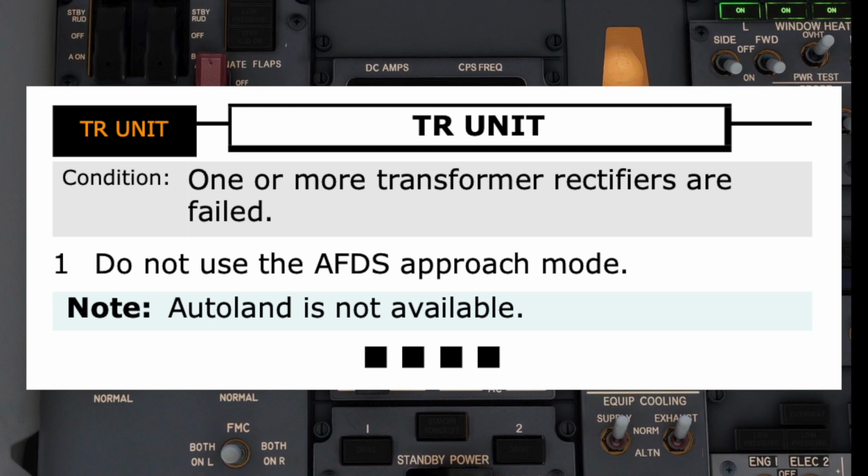Flying the approach without flight directors is referred to as a raw data ILS, and requires extra attention. One thing to be aware of is possible increased weather minimums when flying a raw data approach. Will you still be able to land on the intended runway taking into account these increased minimums? While this checklist has only one step, the ramifications of not having flight directors and approach mode may affect the approach. The pilot monitoring now reads the note.